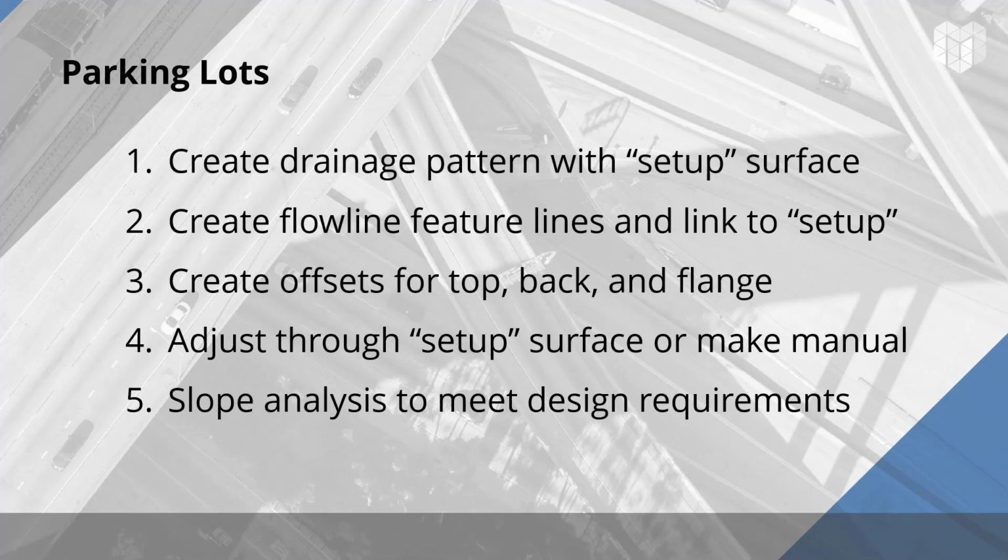Parking lot grading can be one of the most complex things to do, and it can eat up a lot of time. So this is a concept that helps you get a preliminary grading concept before you get into more fine-tuning. With that, we're going to create flow line feature lines, or gutter line feature lines, and we're going to link those to the setup surface.